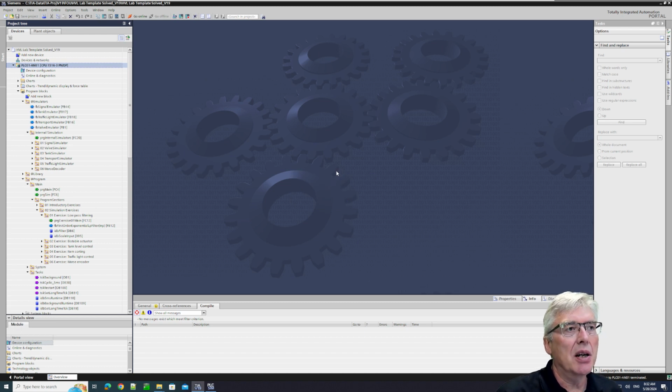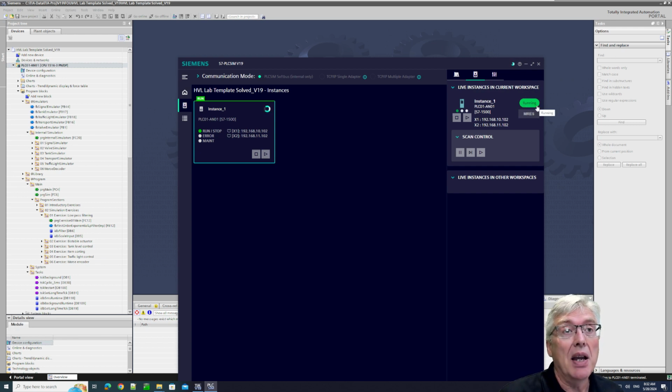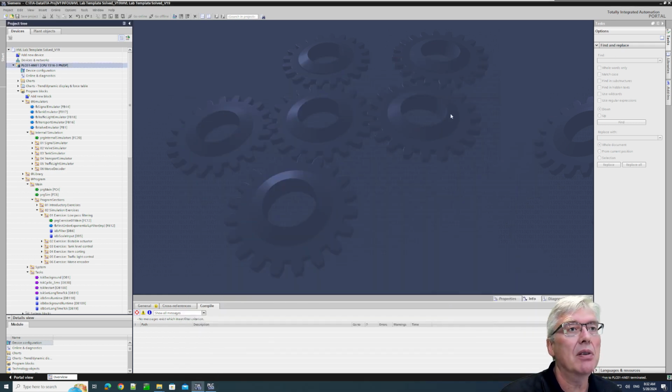So this is like TIA Portal. If it's possible to ask a question, they are going to ask you a question and you have to answer yes or no or something like that. The reason why I selected run was because I want to switch it on. But okay, it's often nice to be able to, let's say, cancel things like that. So now it is running. So now I should be online here. Minimize that one. And now I can test selecting the CPU and say go online.